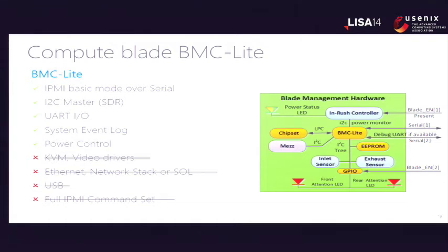It supports IPMI basic modes. There are very, very few IPMI commands, like read the event log, turn the server off, tell me the hard drive status, simple things like that. The power control and event logs are pretty much the two things that are done. There is no KVM, no video drivers, no Ethernet, no network stack, no USB, no support for full IPMI. The simplicity is the keyword.